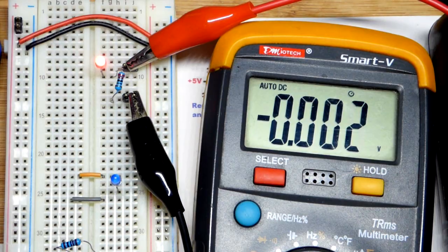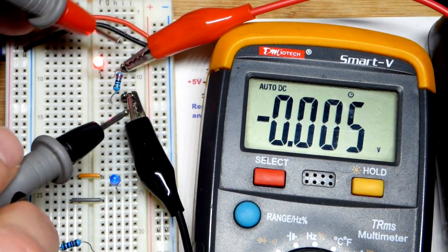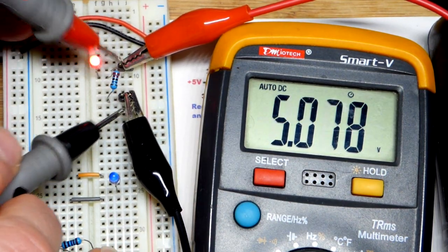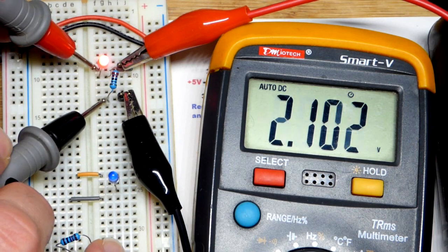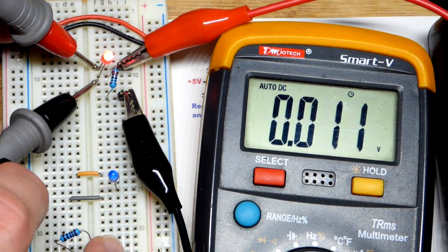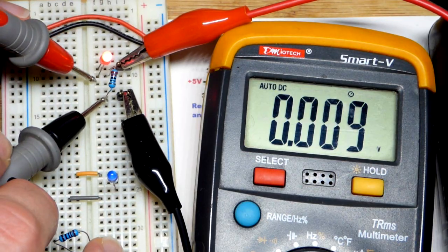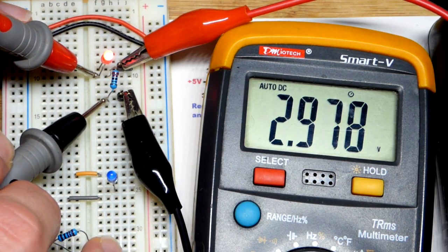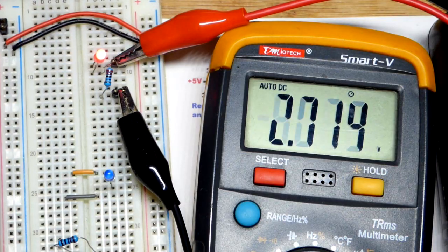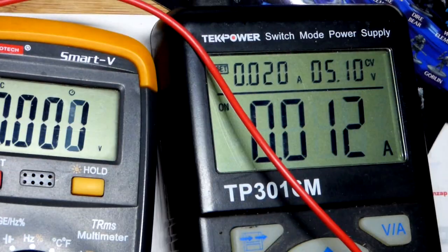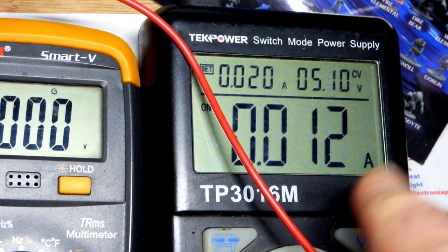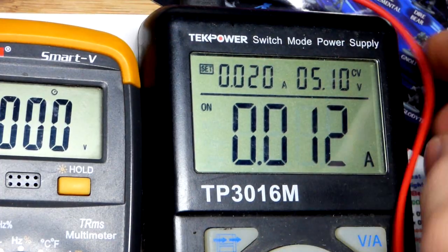So I'll zoom in a little bit. Again, we can measure the total voltage either at the alligator clips or across the components right there. Basically same thing. Red LED is dropping about 2 volts, which gives us about 3 volts across the 220 ohm resistor right there. So we're going to get about 50% more current right now flowing through the circuit than we had before.